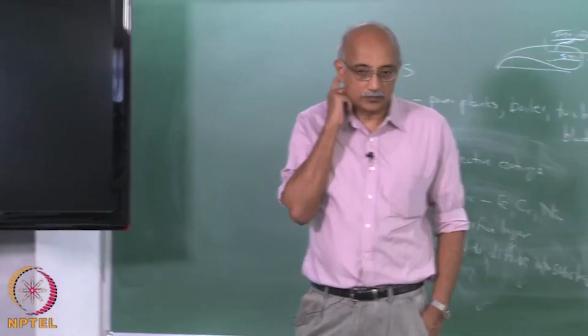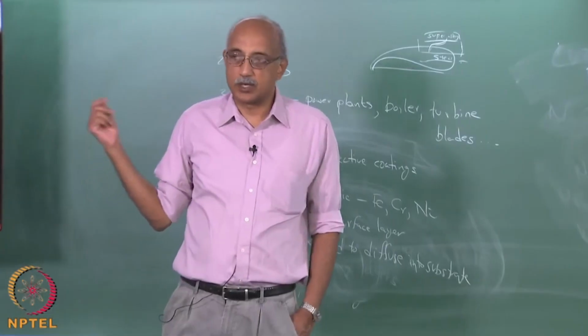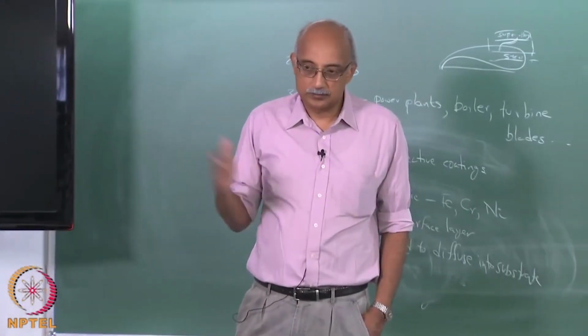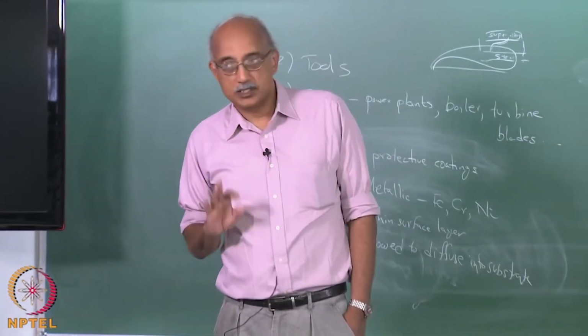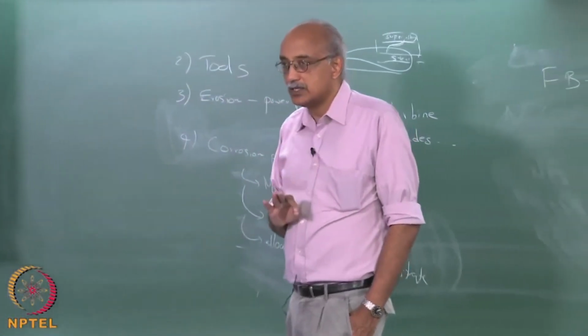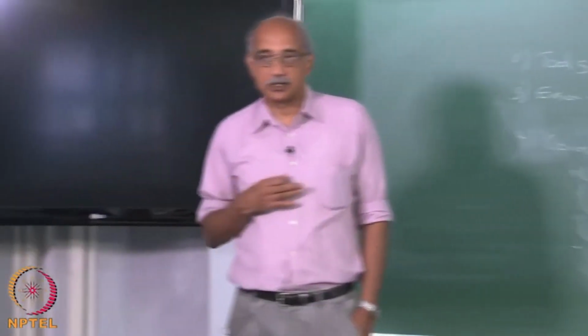So, plasma CVD for coating of polymers, and this can be a variety of polymers. You can coat everything from polyethylene to polypropylene to polystyrene, nylon, PET, anything can be CVD coated, but you do have to do it in a PECVD reactor and not in a low pressure CVD reactor or an atmospheric pressure CVD reactor.